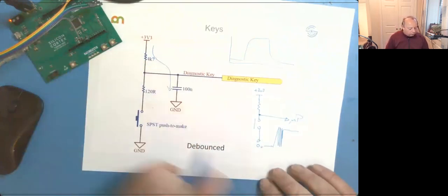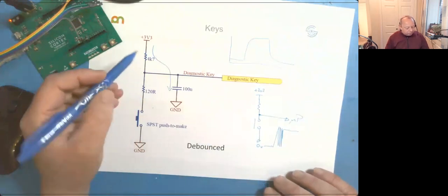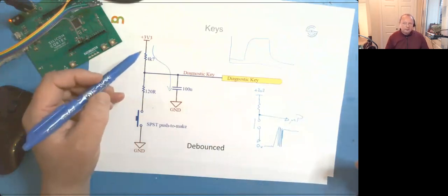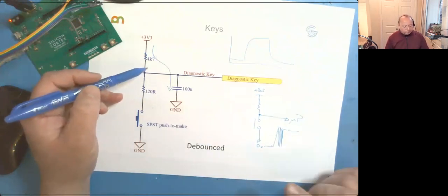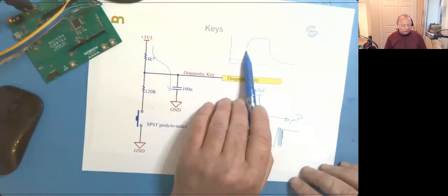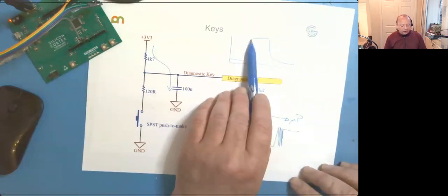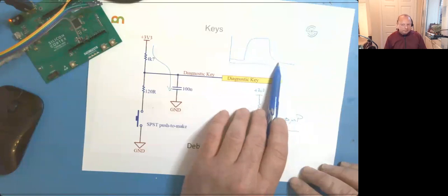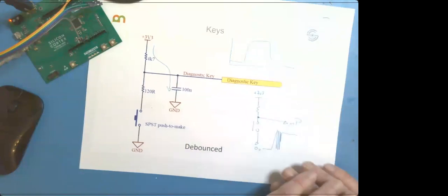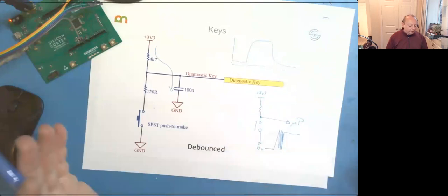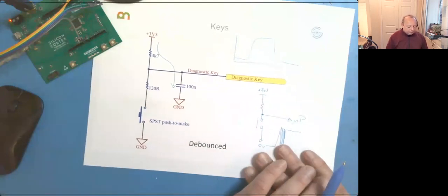So by having these two resistors, let's say the point of the two resistors is just so you don't see switch bounce in either going high or going low. Understood, thanks. Yeah, because you wouldn't want it in either event, really, would you?